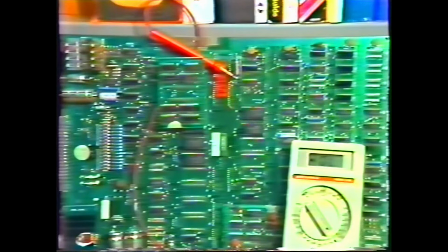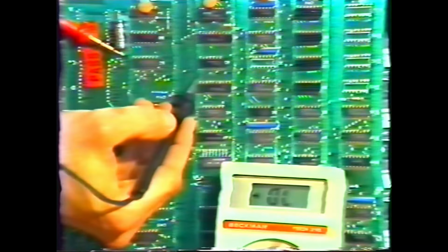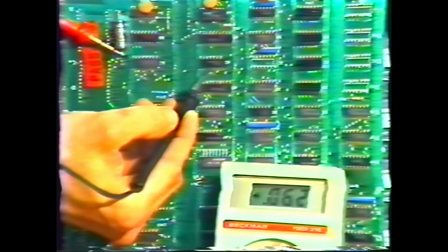Integrated circuits that belong to the TTL family are used quite often in games. When these ICs fail, very often their inputs or outputs will short out, and we can pick up this short with our meter set to the diode test range. This is the only test where we will ground the red meter lead and use our black meter lead to probe each of the pins. A good input or output should read a junction drop like this. But a bad input or output will usually show a considerably lower reading like this.